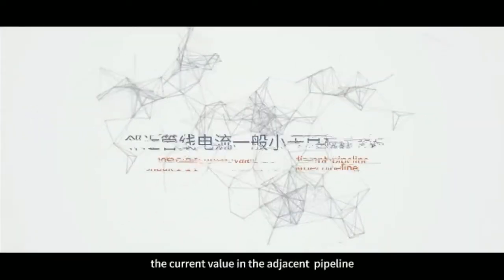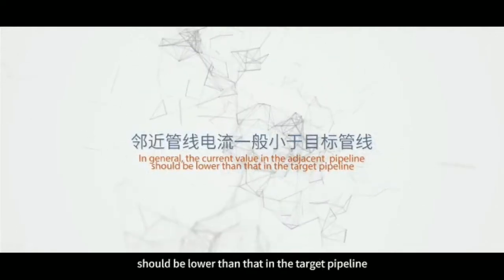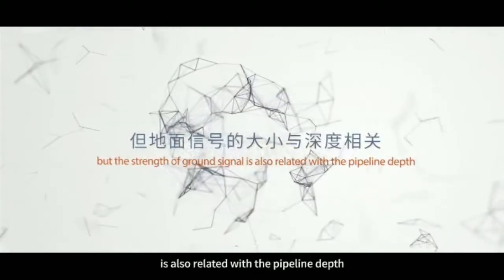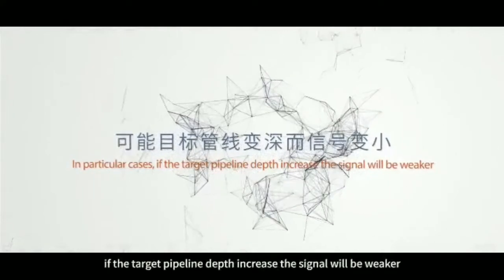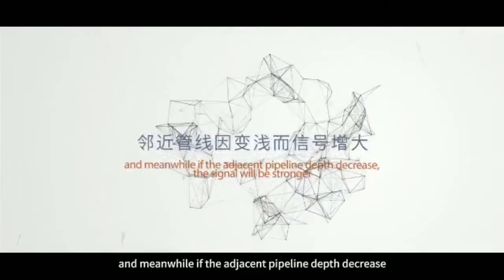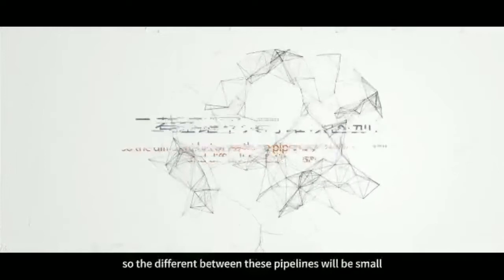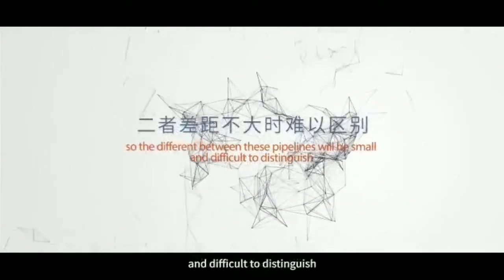In general, the current value in the interfering pipeline should be lower than that in the target pipeline. But the strength of the ground signal is also related to the pipeline depth. In particular cases, if the target pipeline depth increases, the signal will be weaker. And meanwhile, if the interfering pipeline depth decreases, the signal will be stronger. So the difference between these pipelines will be small and difficult to distinguish.